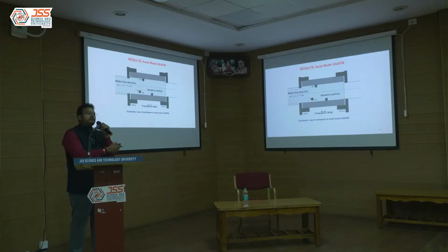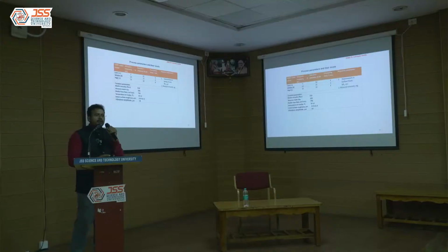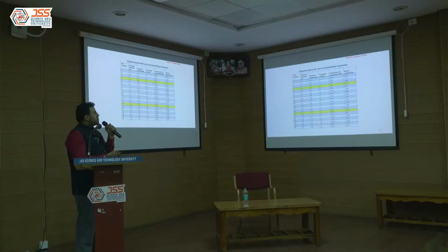And the novelty comes when you vibrate axially: what is the surface response, what are the parameters that are acting, and how the surface finish improves, MR improves, etc., while performing in an axial direction. So that case study also we have done, and we have performed a similar kind of exercise.